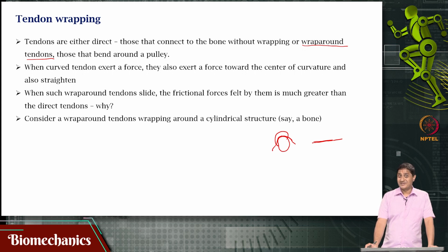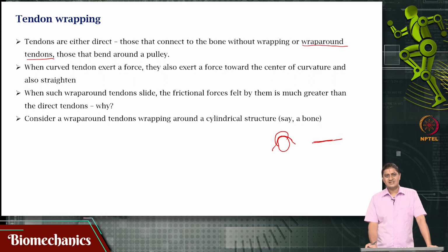We will have to check why, because one likely reason is that the contact area increases. But you would say that contact area does not affect simple friction mechanisms such as Coulomb friction. Actually, this is not true. In many cases, contact area has a very important role in deciding the amount of friction and resistance. The coefficient of friction might not change, but the amount of force felt will be affected by the contact area.